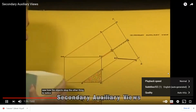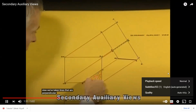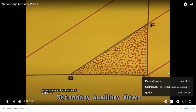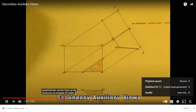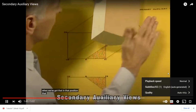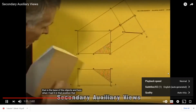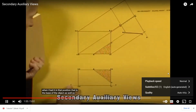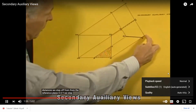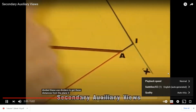Okay, the other thing to note is that to construct that view, we've taken lines that are parallel with this line BF. So we've taken these construction lines up. The distances we stepped off relate to this reference plane XY. If you notice that when we've got that in that position, that is the base of the object. And here, when I had it in that position, that is the base of the object as well. So the distances we step off from the reference plane XY, we step along, we divide these to get these distances from the plane X bar, Y bar.